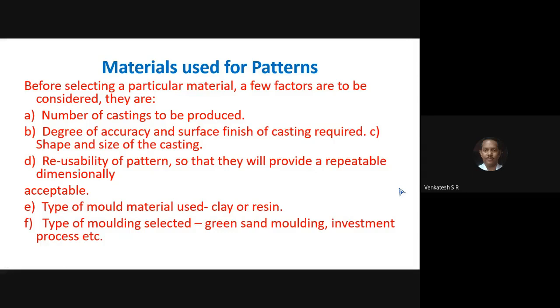They use sand casting with binder, clay and resin. What is the purpose of clay or resin? That is nothing but bonding of the sand particles. Next, the type of mold selected: green sand molding, dry sand molding, or investment casting process, etc. This is very, very important.